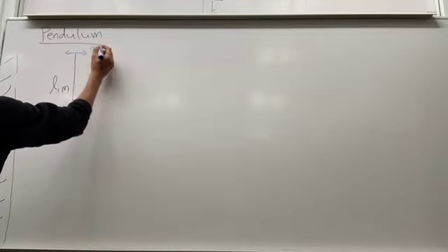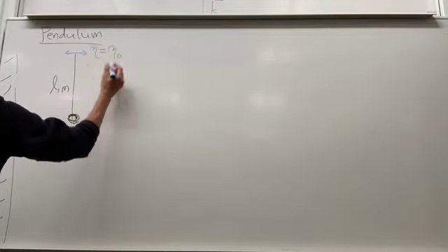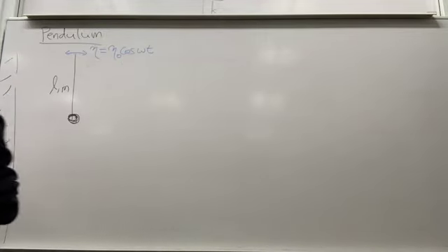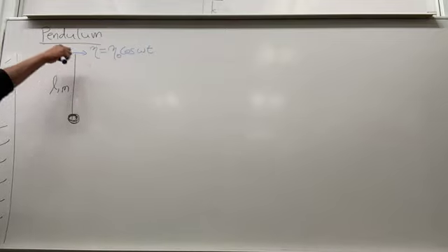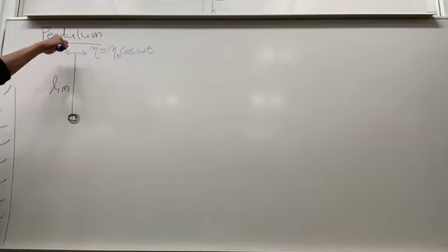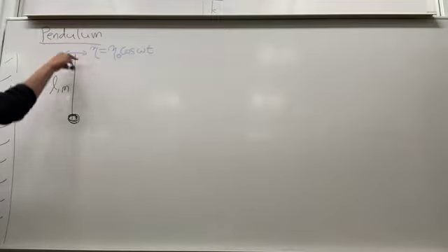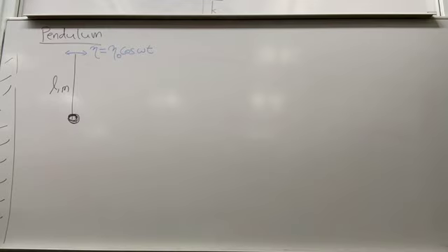Not a force, but displacement, which is some constant times cosine omega t. Right? This is a displacement now. So I'm holding the pendulum and I'm moving it right and left. I'm displacing it, so eta is the displacement here.